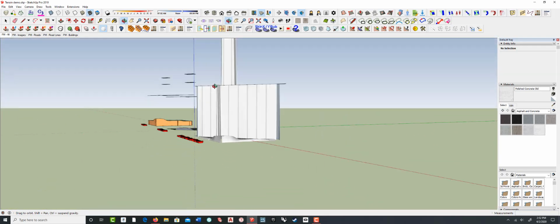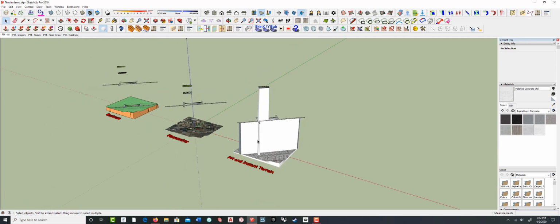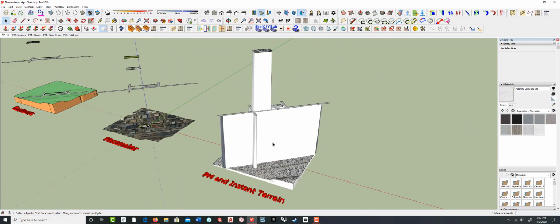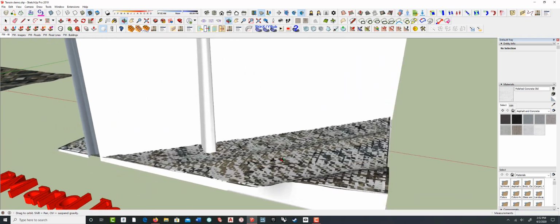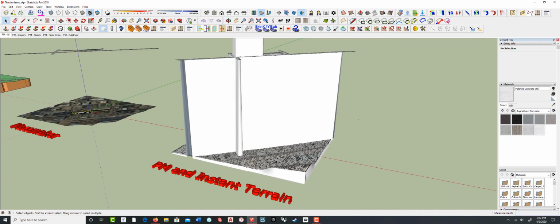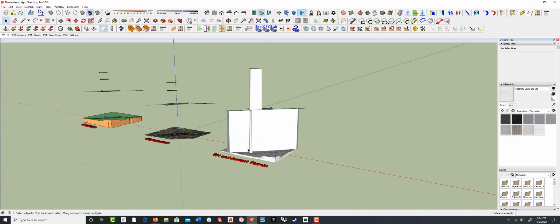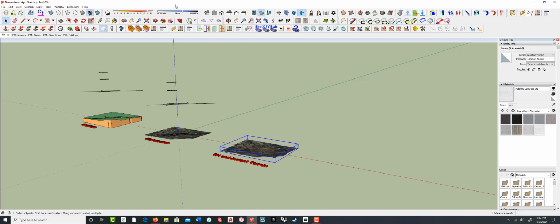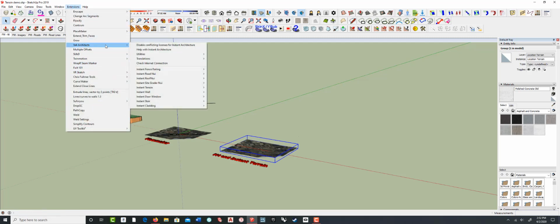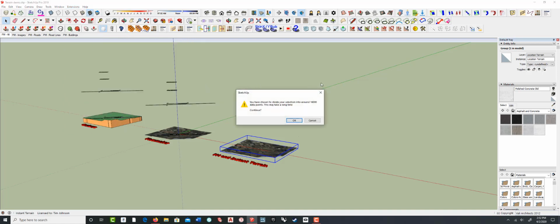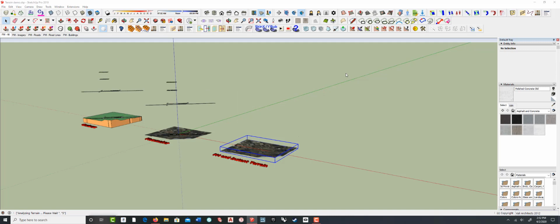Unfortunately, well, maybe not unfortunately. Good example. One of the things about Mr. Valley's plugin is it looks at everything that's here. So you can see what it's doing down here. It's starting to look pretty nice, but because I have these other objects up above, I'm going to have to redo that. So I'm just going to cut them out of there because even though I have this selected, it's looking down through the entire SketchUp model, making a terrain over everything that's visible.